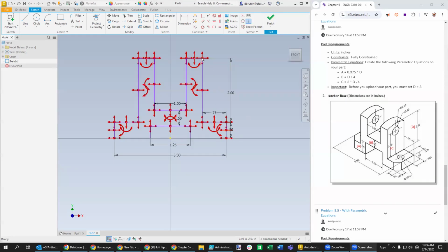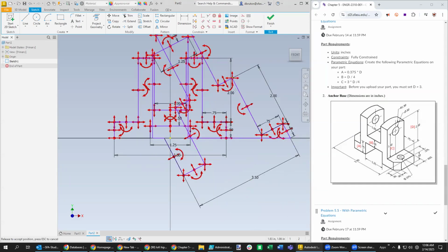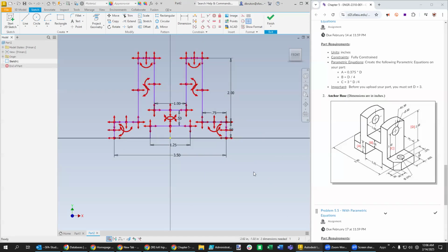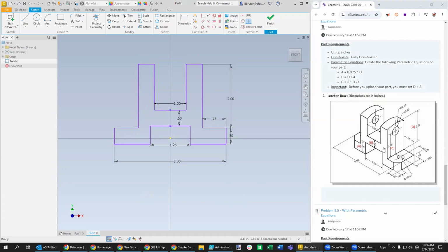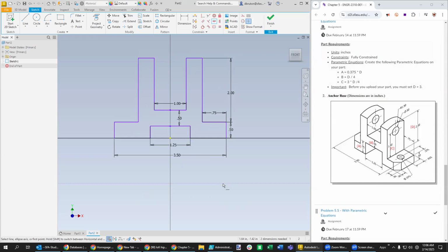Yeah, so check this out. You can hit this and you can see that I got a rotation problem also here. So I Control Z on that. And let's go Control Z back to this one. I think I had the video off when I was showing this part. We want these things to be horizontal at that point and this point right here. We also want this to be horizontal, and that's what we were really looking for. Now, hopefully, we can go back to this point that we originally did and make this right here 0.75, and it will drive the part up instead of down. So it's about establishing that anchor to begin with, and now we have a fully defined part.